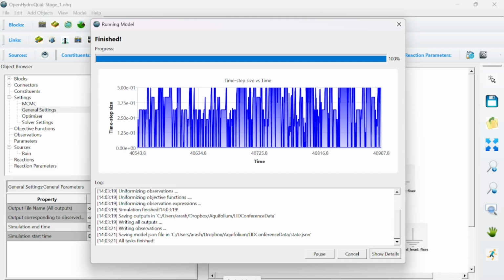So if you want to model an LID for most of the year, not much happens, right? When you don't have rain and things like that, it's just dry. When not much is happening, it can actually use a larger time step. And then when you have a rain event and you want more detail, it's going to use smaller time steps, right? So that's what you see.